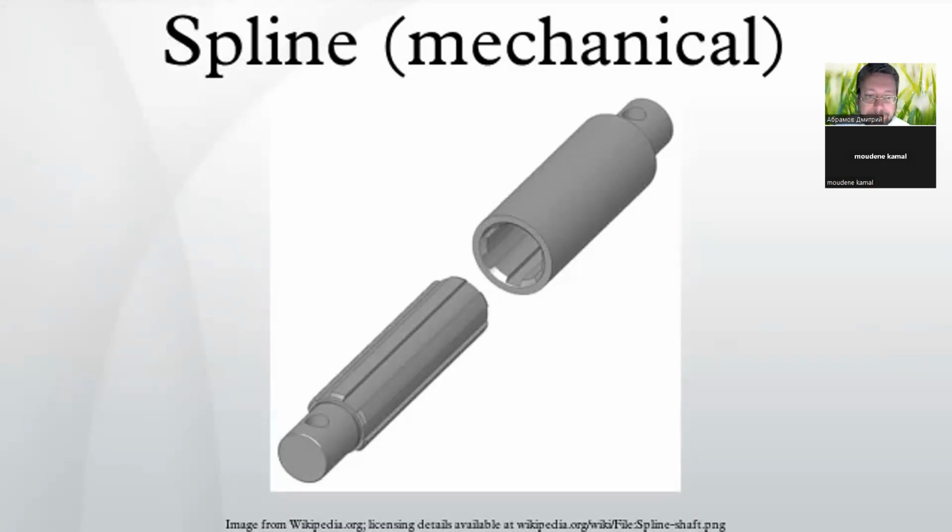These are used on small diameter shafts. Helical splines, where the equally spaced grooves form a helix about the shaft. The sides may be parallel or involute. This can either minimize stress concentrations for a stationary joint under high load, or allow for rotary and linear motion between the parts. Ball splines, where the teeth of the outer part are implemented with a ball bearing to allow for free linear motion even under high torque.